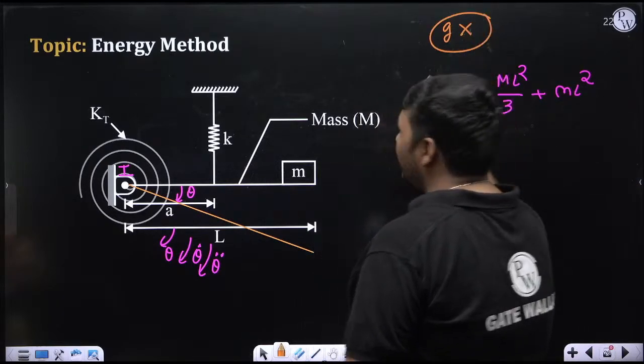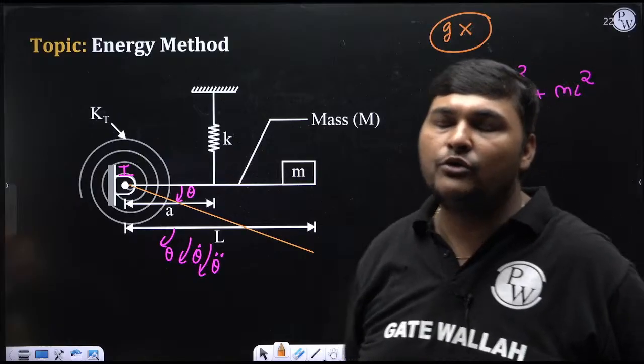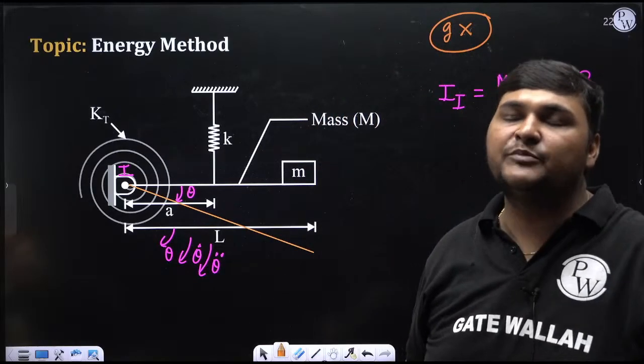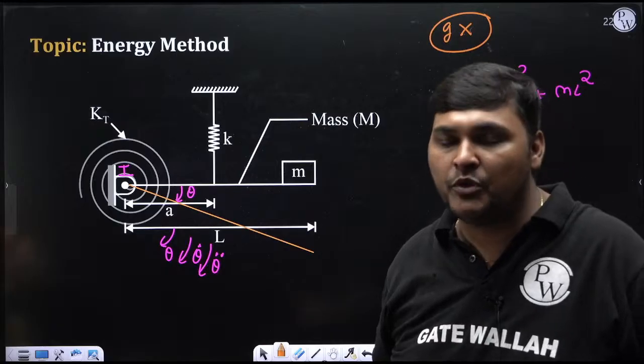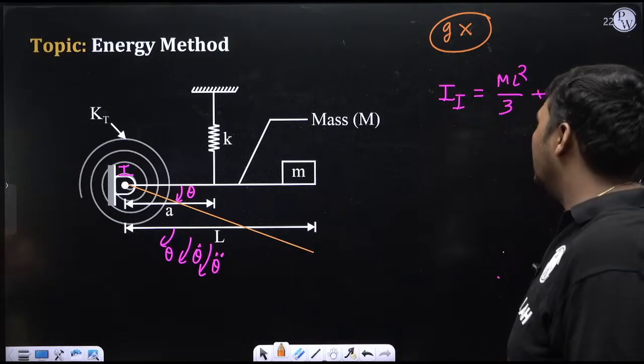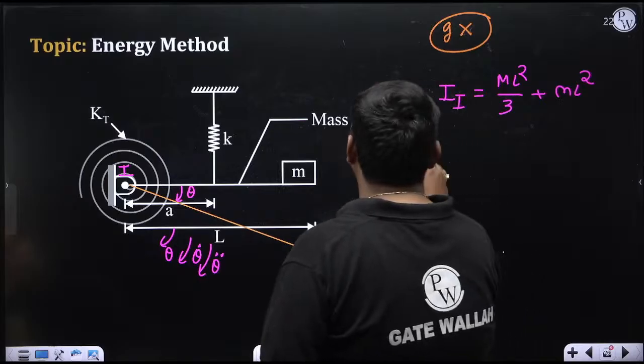Okay. So when you calculate potential energy, only calculate due to stiffness of the spring, and in that formula don't take total displacement, take the displacement of the spring from mean position. Okay, we will not consider datum energy. So for total energy, first I am calculating kinetic energy.